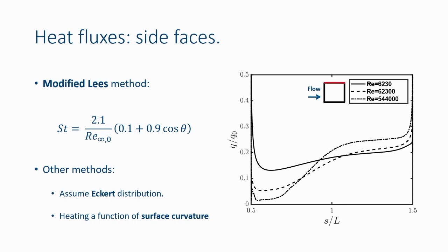So obviously, we see that there is a strong effect of the separation bubble. With the fully developed separation bubble, the heat transfer rate underneath it is an order of magnitude smaller than the region outside of the separated flow. And so this, I would argue, would play a significant role in heat transfer to the corner.